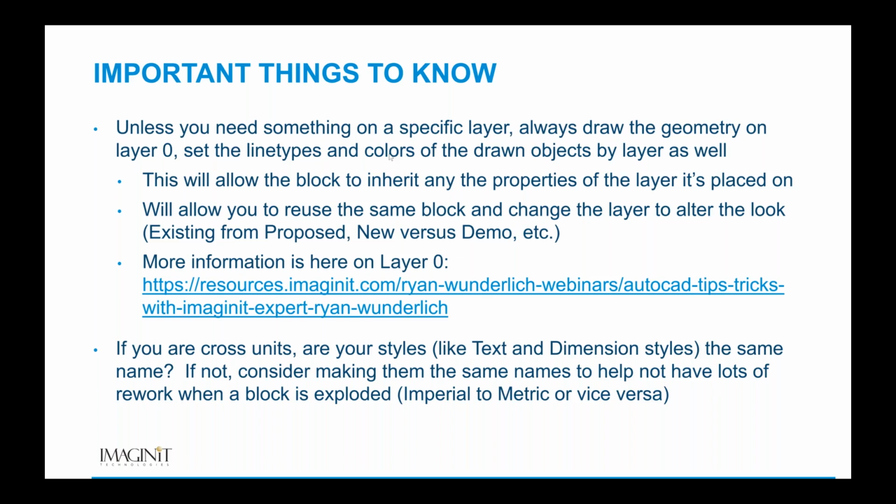So imperial to metric or vice versa. If they're the same name, they will inherit the same properties. Everything will be normal. If you're simply inserting a metric block into an imperial scale drawing and you explode it, everything goes haywire because names are different. That's usually the problem.